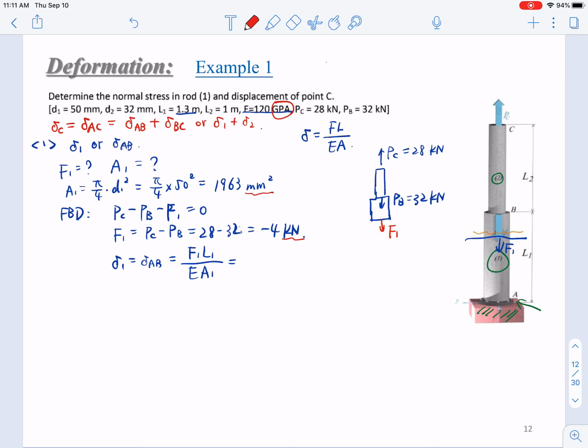We have known that MPa equals 1 Newton per square millimeter. So this is the compatible unit system. If you use this system, you just need to convert everything about Pascal into MPa, everything about kilonewton into Newton, everything about cross-section area or length into millimeter, square millimeter. So this is a compatible unit system, millimeter, Newton, MPa. So we just convert everything into this unit system.